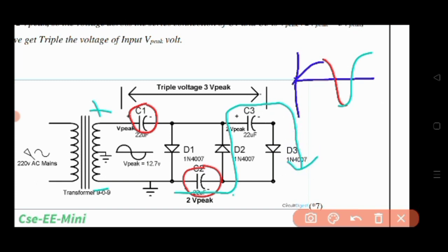In this way you can see here, current will flow like this. According to the forward bias condition of diodes D2 and D3, it will go like this. Or we can also understand, as I have already said, that D2 will not work in this condition of transformer polarity. So we can understand the circuit like this.